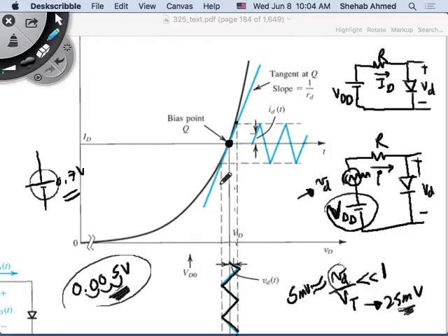But what did I require? Here, what is the diode doing actually? If I'm making a small change in the input voltage, what is it doing to the current? Is this change equal to this change? It looks considerably larger, right? So I'm actually amplifying it. So the diode is able to.